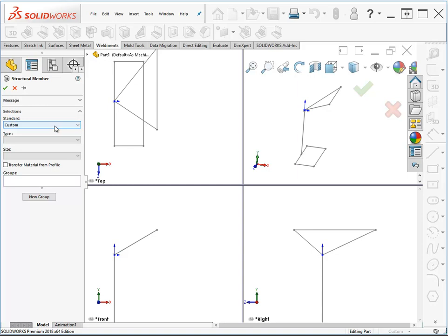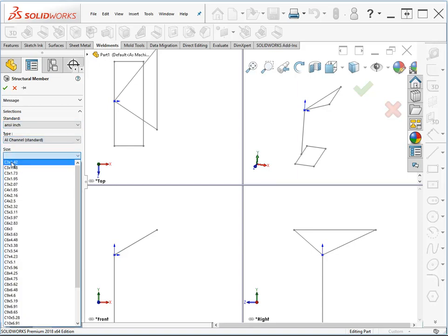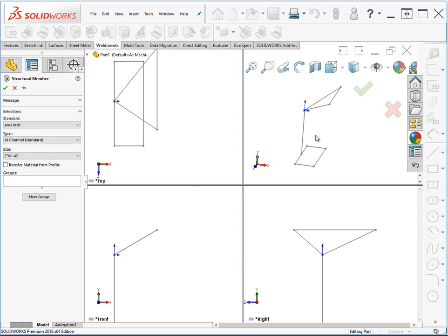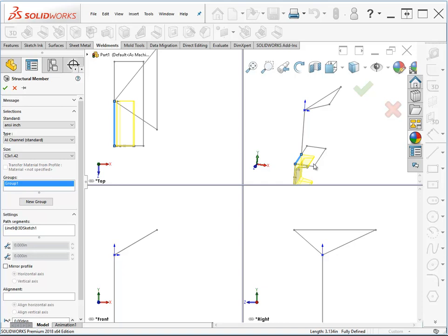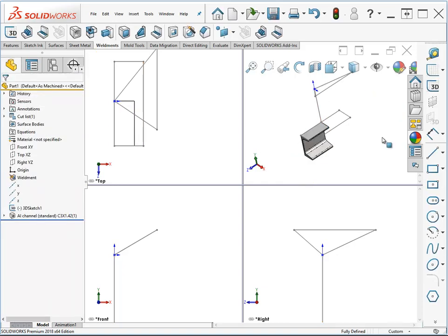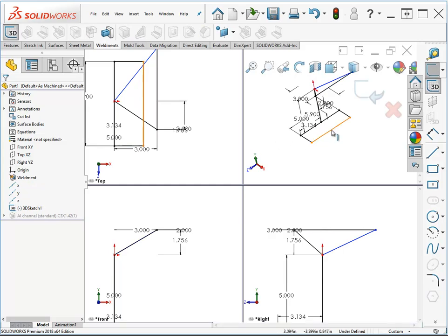Lumber definitely fits kind of the stock shape and straight length scenario that most of your weldment material fits as well. So from here, we select a type of material from the standard, we select the size, and then from here you can start applying this to geometry. All right, we can go back to our 3D sketch and adjust some sizes.